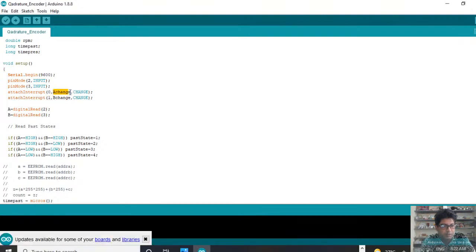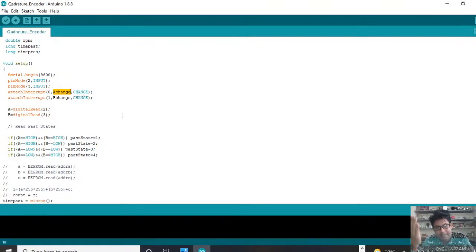And I am using one service routine called channel A change and B change. The type of interrupt means whether it is rising edge, falling edge, any change, or always high or low. So I am using any change.